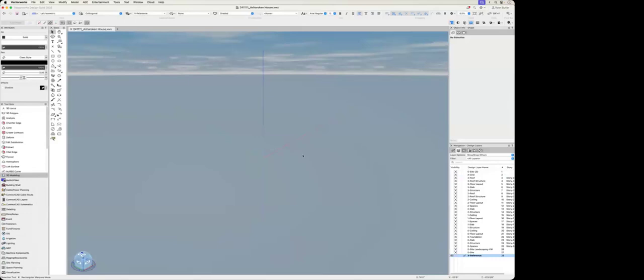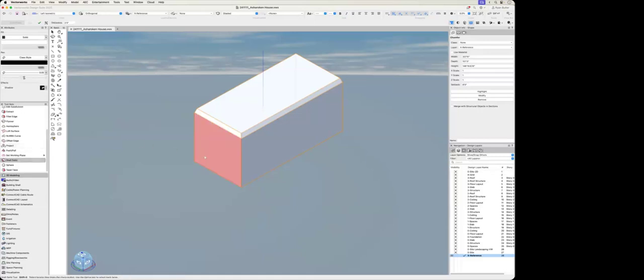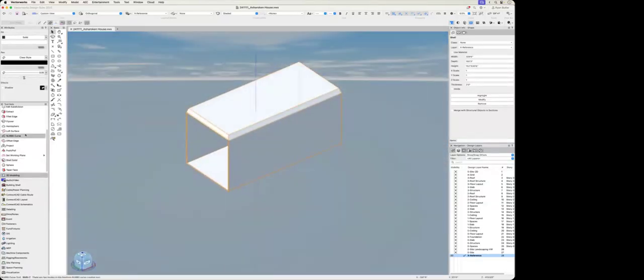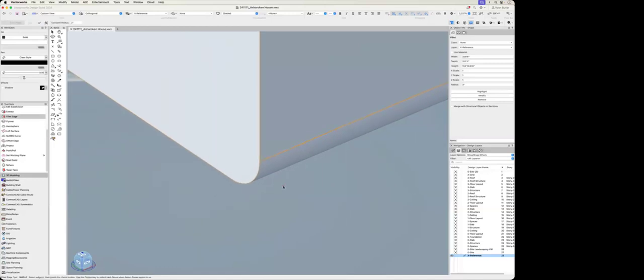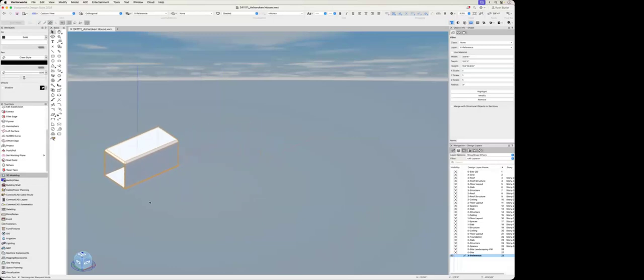With the 3D modeling toolset, I can model in a freeform fashion using a bunch of different tools, for example, chamfering in the edges of objects. I can shell a solid. You can set a thickness for the shell as well. You could do other things like fillet edge. That's very small. Like so. And you could also do push-pull modeling too.